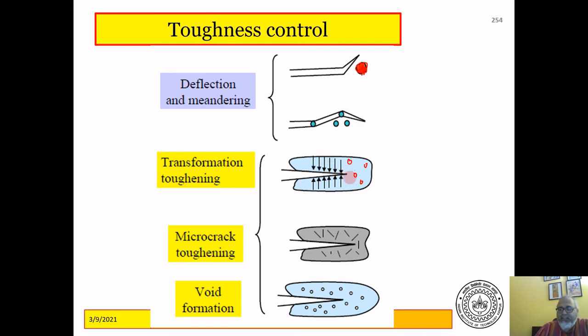So when a crack propagates, there are high tensile stresses at the tip of the crack, and these tensile stresses will lead to the transformation of these particles from one phase to another, and the transformed phase will have a slightly higher volume. These slightly higher volume materials are going to impose a compressive stress which will tend to close the crack, thereby making it a little more difficult for it to propagate through, because as it propagates there are particles transforming and increasing in volume and imposing a compressive stress on the path of the crack.